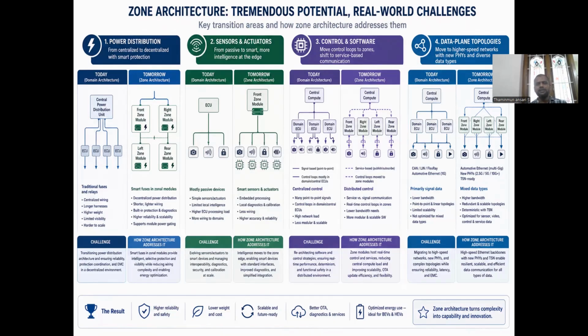From this, they are controlling the static current leakage. When the components are not used, we need not spend the current. When a particular sensor or actuator is not used, we need not spend the current. That's why we have the concept of sleep in automotive.